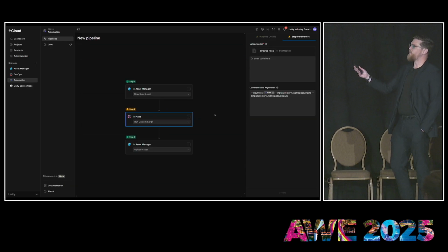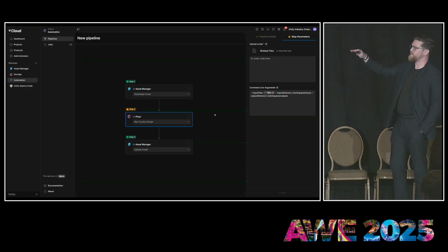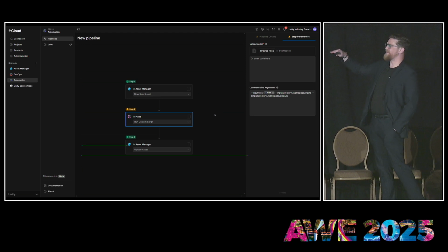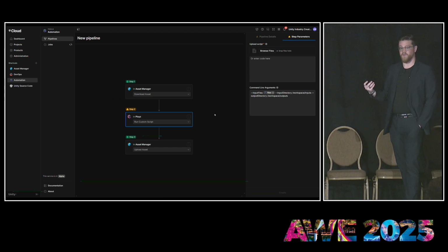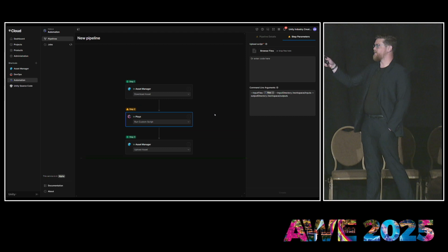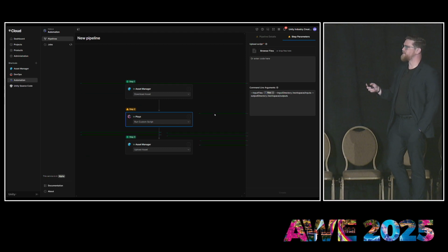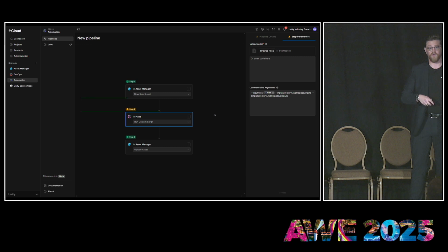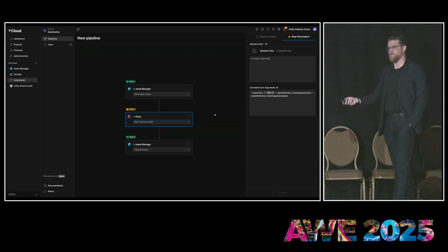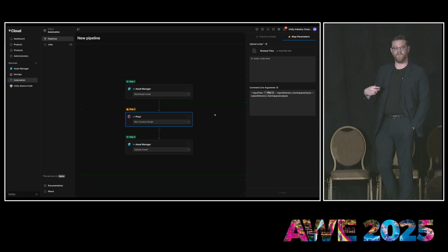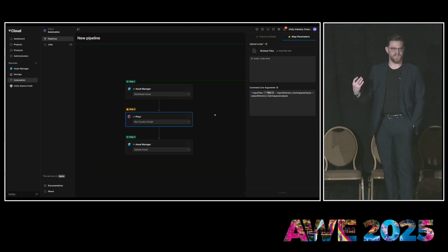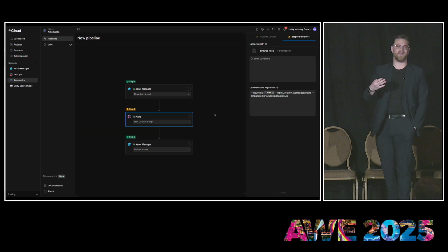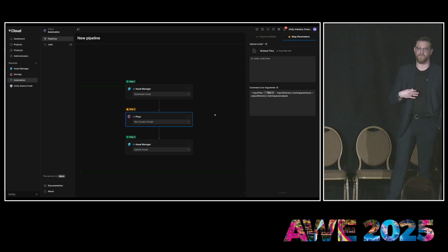What that looks like from a UI UX perspective is just another tab right there within the Unity Cloud dashboard, underneath Asset Manager, where you can create from a node-based system these steps and these recipes that you'd like to repeat. One of the coolest things that I think to point out on this slide is that you'll notice that the second node here is actually a run custom script node. So if you've been using Pixyz or you want to use Pixyz for more in the weeds transformations, you can actually do that and then leverage those custom scripts as a node within the system and automate that process for users who might not need or want that level of sophistication in Pixyz.